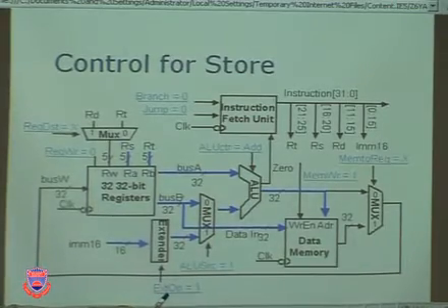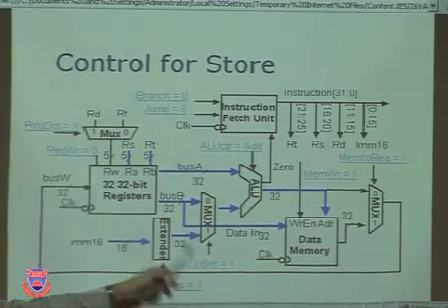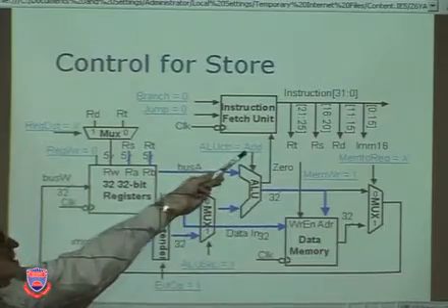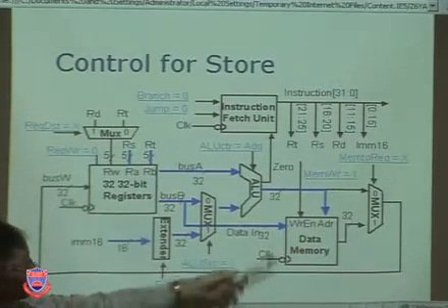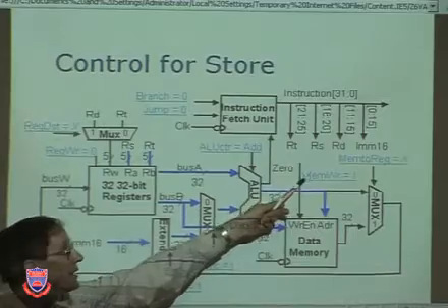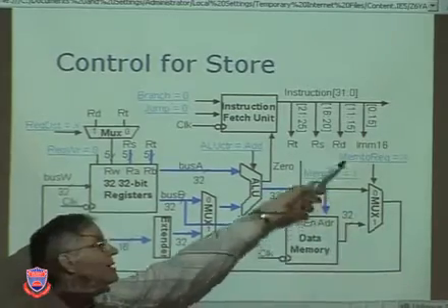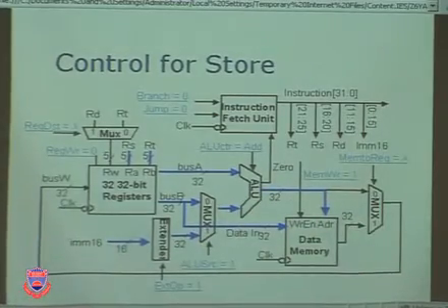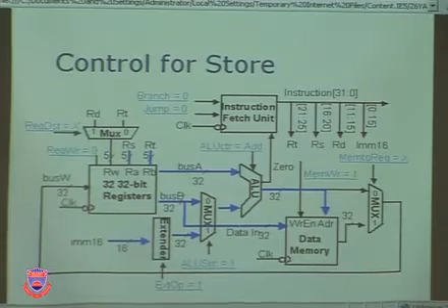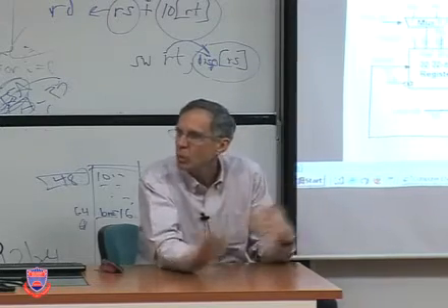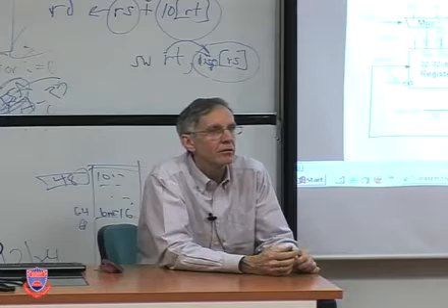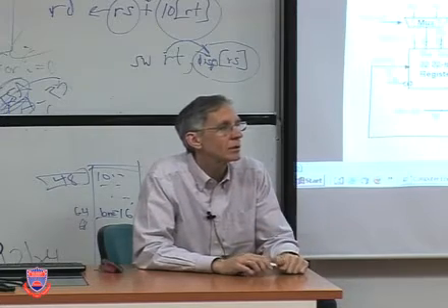This, of course, does matter. It needs to be sign extended. This matters very much. I need to choose this lower one. That needs to be add. This says don't branch or jump, so I sequentially go to the next one. And this must be write. And back over here I have a don't care. Everybody see that? I'm not sending anything through that mux to come back to here, so don't care about that value. So we have 1s and 0s and don't cares, depending on what we want to do with the control signals. I mean with the units we are controlling.